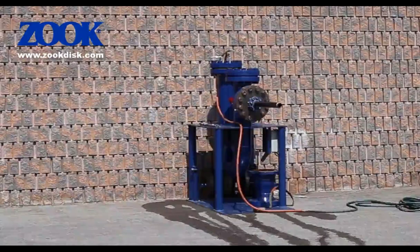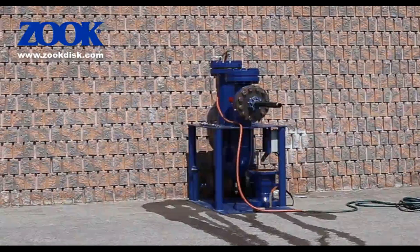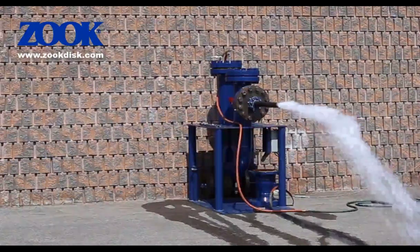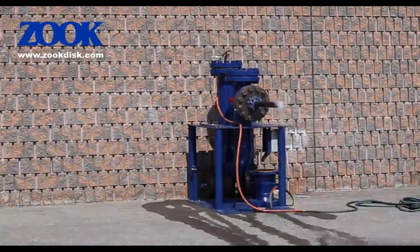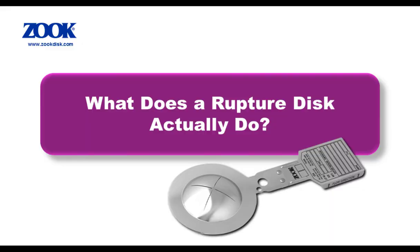Here's another example using water. Rupture disks are custom designed safety devices, and they can be engineered to function in both gas or liquid service, what we call compressible or incompressible service. Compressed gas has significantly more stored energy than liquid, and the burst event is much more violent. In terms of rupture disk design, a gas burst poses significantly more challenges to rupture disk engineers.